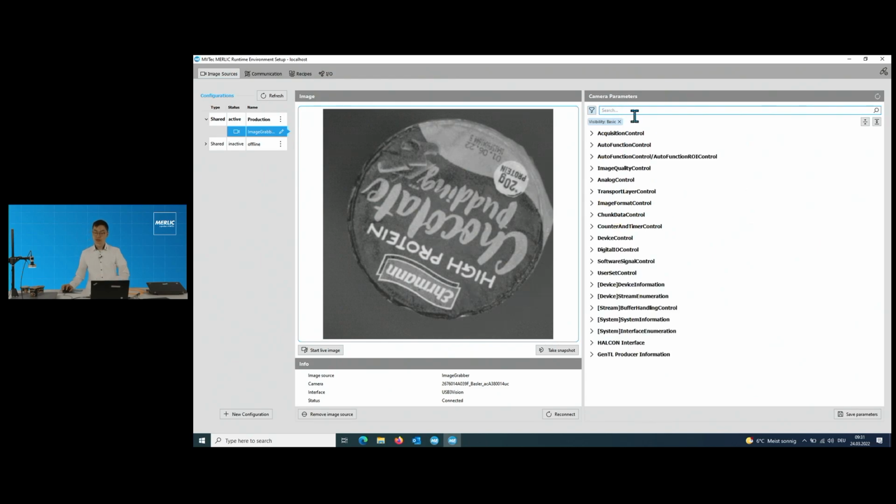And now, after setting the camera parameters, I want to save them. You can see here, save parameter we can use, but there was a problem. We didn't know if the parameters are persistent or not. What is the difference between persistent and non-persistent parameters? Simply said, we can only save persistent parameters. For those non-persistent parameters, we are not able to save them, as once the camera is plugged out, these non-persistent parameters will be restored into default.